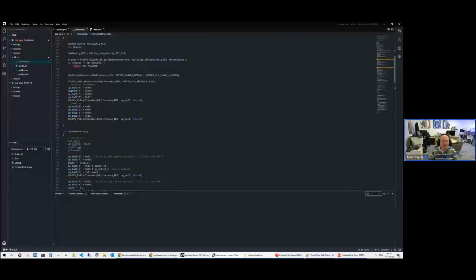And then we're setting up some internal buffers to read and write the PMOD DA4. Once we've set those values, they essentially set the internal reference to be used. In this first one, we do a polled transfer, so it will transfer those 4 bytes into the SPI, and then it will come back and we will power up the PMOD DA4.